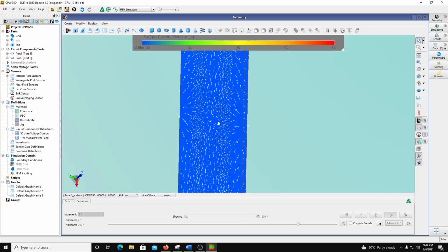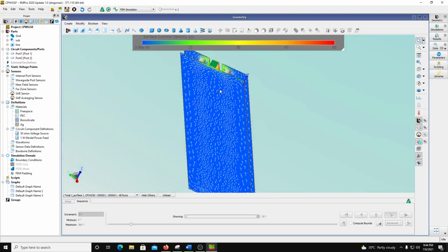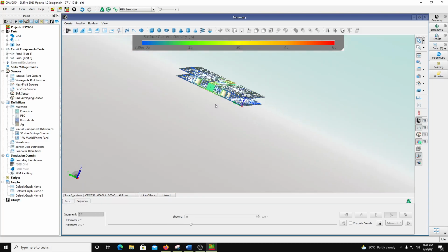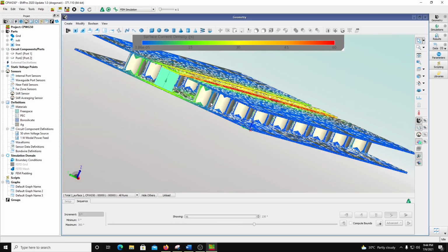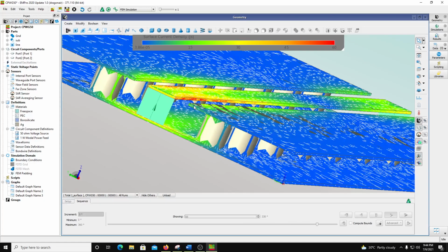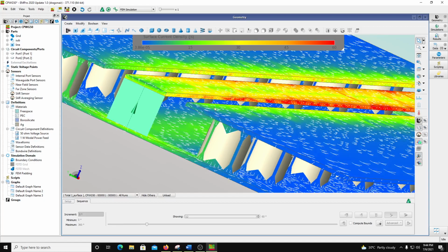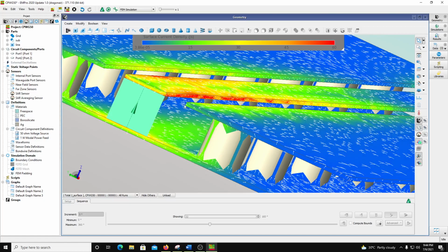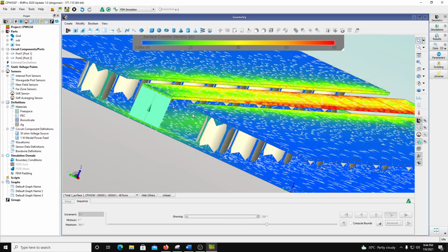So now you can see in animation how the currents are there in the line, the coplanar ground, and what's happening in the ground plane. The ground plane is almost silent, you see, almost silent, right? It's the coplanar grounds which are nearer, right? So if you remember, the height of this substrate is almost 100, while this gap is 50. So the termination for E field is going to be to this ground, not to that ground. Okay, so what is significant is this gap, not the height. Okay, so that is a CPWG line.